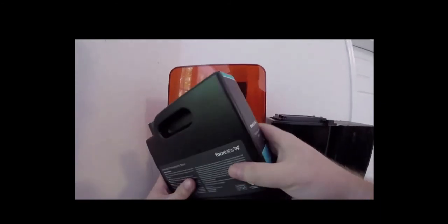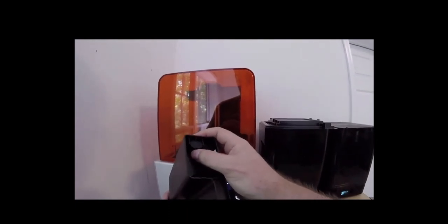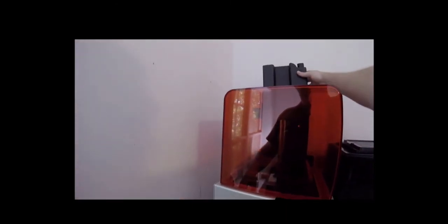This is the cartridge. If you haven't shaken this already, you're going to want to shake this for up to 2 minutes. The other thing I like to do is check the bite valve here on the bottom and just make sure that it's opening properly. Sometimes they get stuck, and if you manually work this with your finger, you can ensure that's not going to happen once you put the cartridge in the printer. So just make sure that's opening up, and then go ahead and drop your resin cartridge into your printer and pop the air vent valve open.